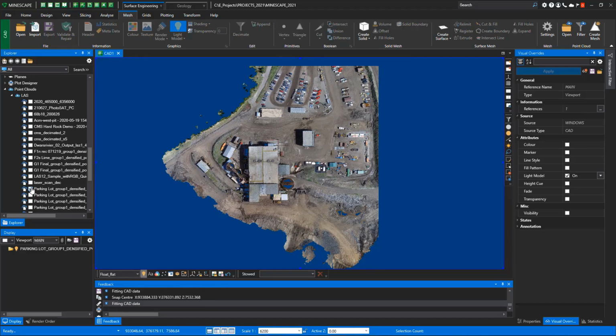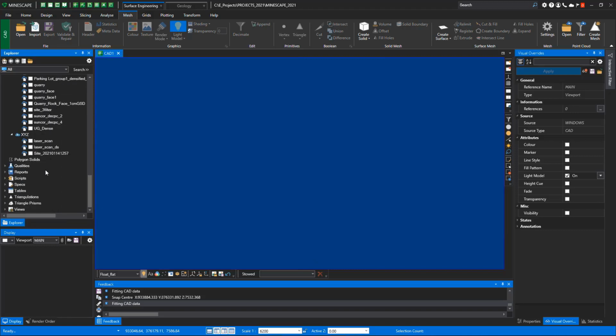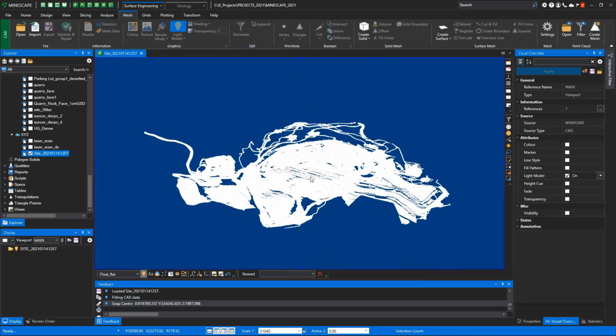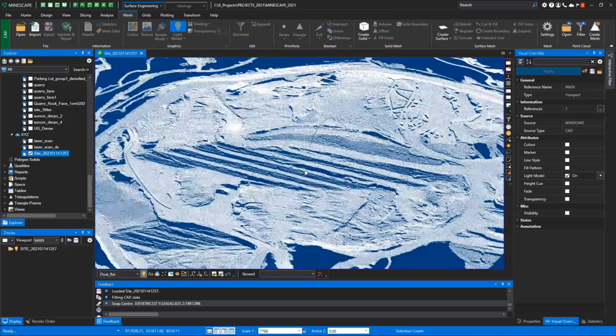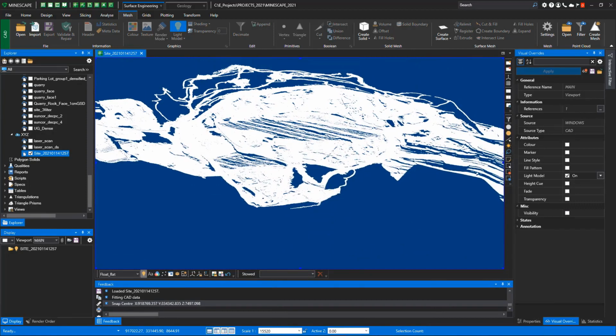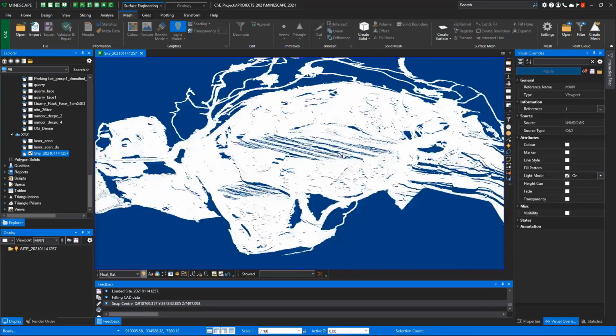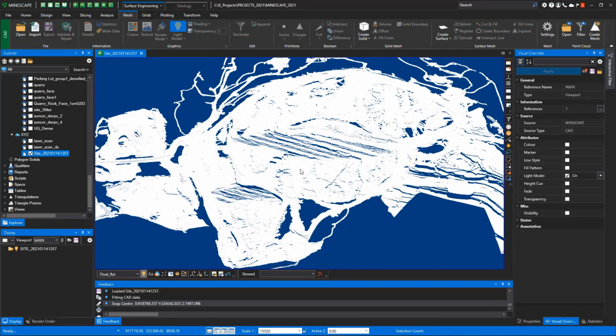Now, the other thing we've done is we've given you the capability to bring in XYZ data. Instead of bringing XYZ data into a design file, you can just bring it into a point cloud. There's some XYZ data, and you can see it's really dense data. It's EC northern elevation. And so instead of bringing this into a design file, you can just load it right here, mesh it if you want to, and use it to digitize. Okay, I'll turn that off.